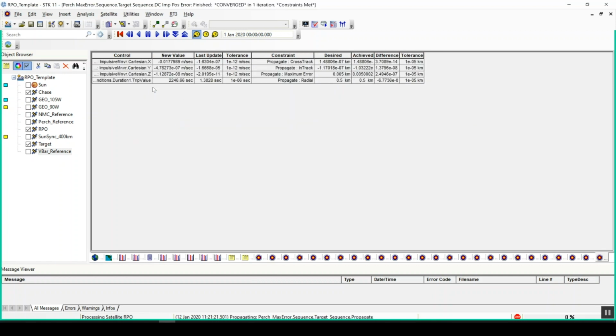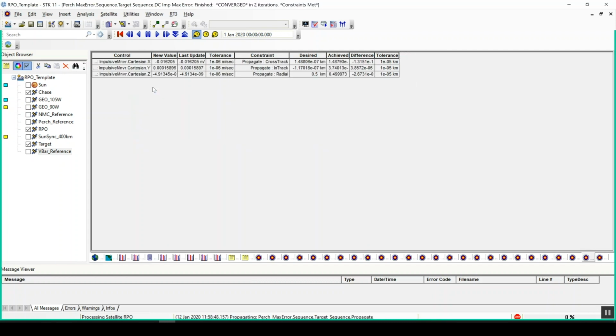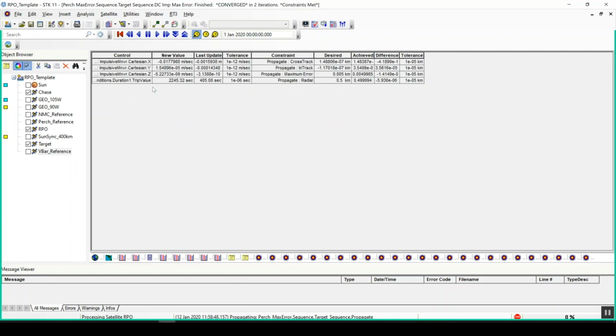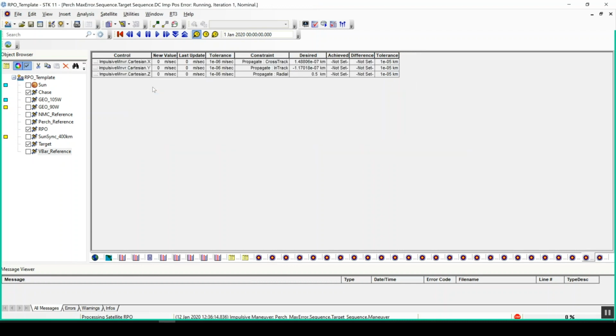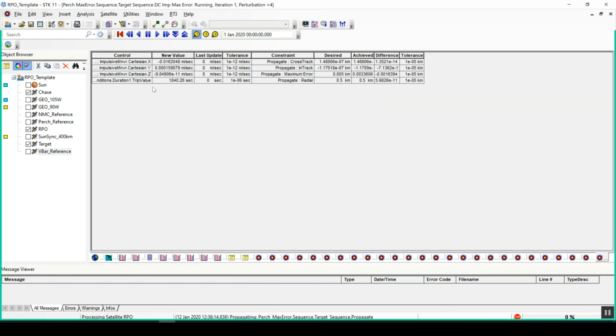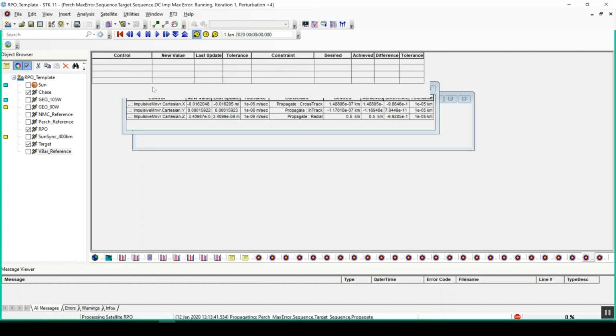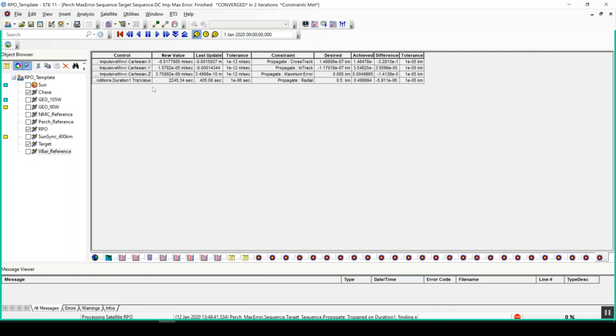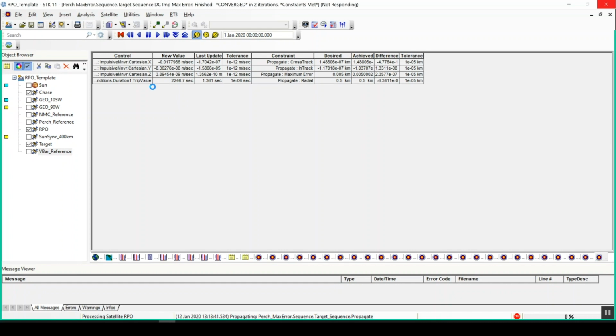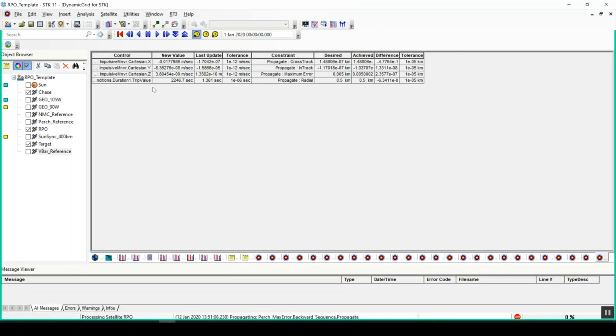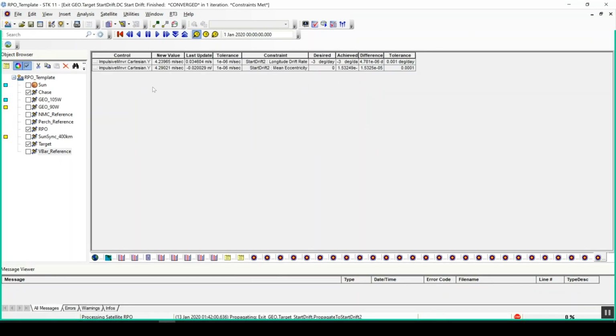Now we're going to let it drift for 12 hours, letting it go, stopping the perch essentially. So the perch gets stopped, and we let it drift naturally because it will. That's not a stable point at 500 meters on the R-bar. And then when we get 12 hours later, half a rev later, we're going to initiate a sequence that lets it drift naturally at 3 degrees a day to the west and leave the scene safely.